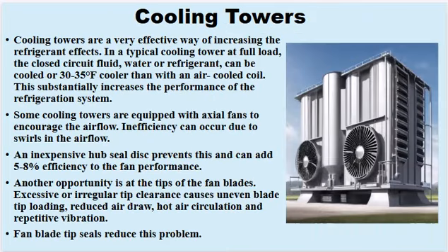Cooling towers. Cooling towers are highly effective in enhancing the performance of refrigeration systems. At full load, a typical cooling tower can cool the closed-circuit fluid, water or refrigerant, by 30 to 35 degrees Fahrenheit more than an air-cooled coil, significantly improving the overall efficiency of the refrigeration system. Some cooling towers are equipped with axial fans to boost airflow, but inefficiencies can arise from swirling air patterns. A simple solution to this problem is using an inexpensive hub seal disc, which can improve fan performance by 5 to 8%.